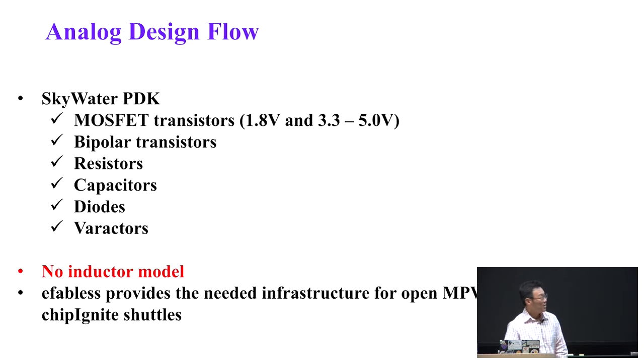And if time permits, I would also like to share another tape-out we are working on, which is just a pure digital circuit design. And efabless provides a really good series of scripts, so that if a student just clicks one button, there's a script tool that generates from RTL all the way to the layout, and also integrates it into the entire chip. But there's a supplemental slide.